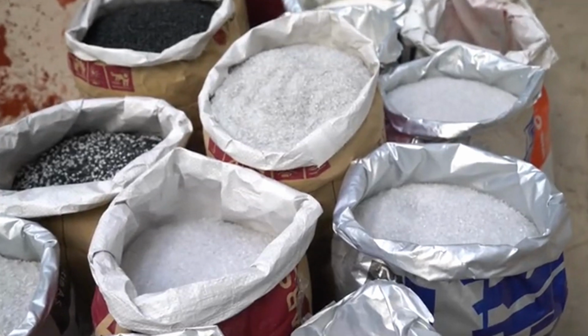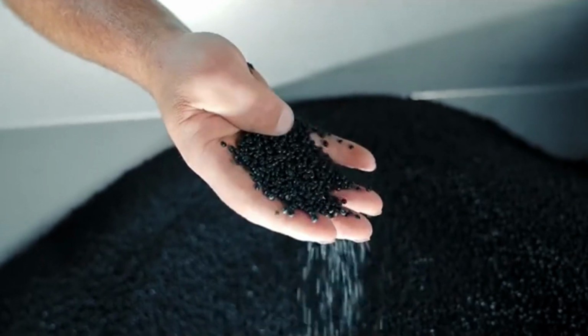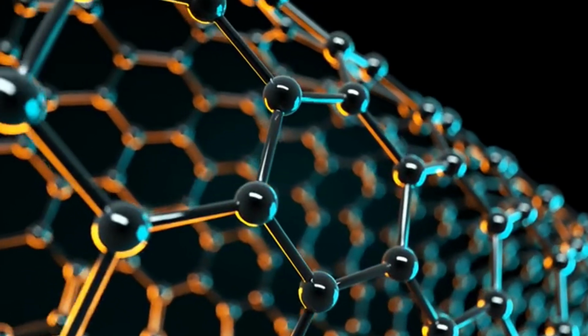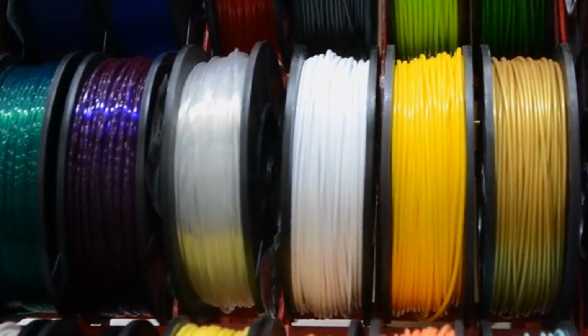Injection molding is a widely used manufacturing process for producing various plastic products. The basic steps are as follows. The first is raw material preparation. According to the use of plastic products and requirements such as strength, toughness, transparency, etc., choose the appropriate plastic raw materials. Common ones are polyethylene (PE), polypropylene (PP), polystyrene (PS), polyvinyl chloride (PVC), acrylonitrile butadiene styrene copolymer (ABS), and so on.